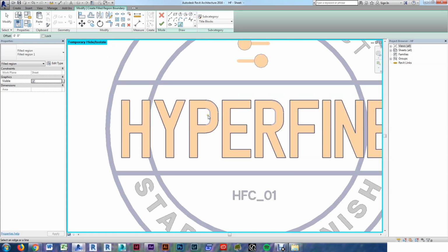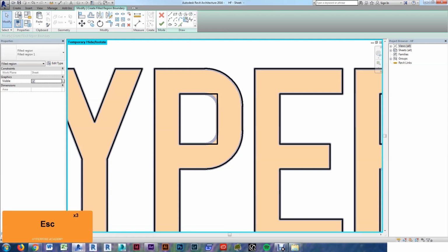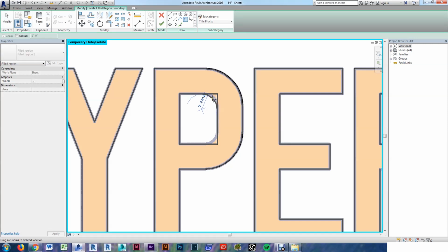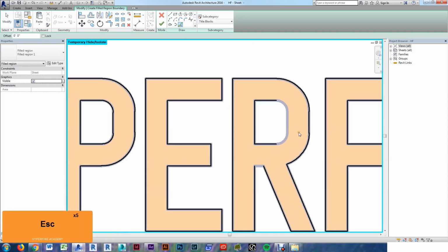So this is only a small fraction of an inch right here. So what I'm going to have to do is make this a square. It's not gonna let me draw that circle directly as a circle. So now that I have it squared out, I'll use the fillet arc command. I'll select both lines, and then it lets me round that corner out. If it was smaller than this, it might not work, but this is large enough that it'll work.